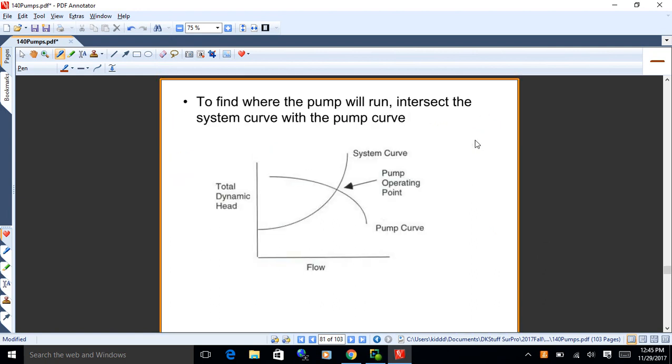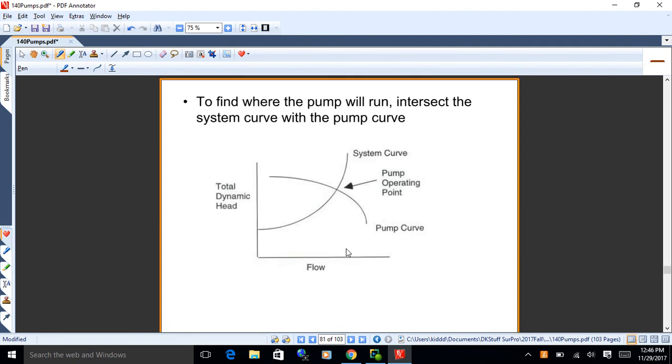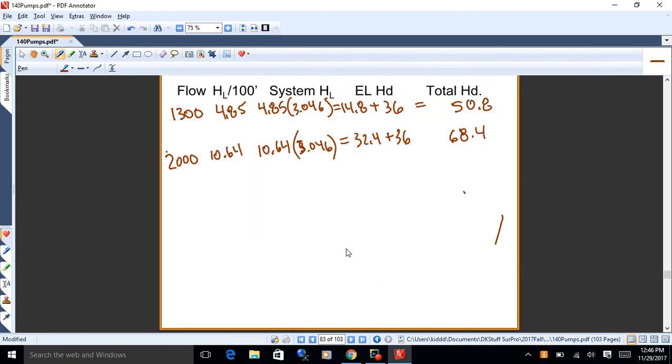Okay. So when the pump gets up to 2,000 gallons per minute, it's at 64, was it? So that's about here. It's getting there, but it's going to keep going. It can still do more, so it's going to pump harder. So let's try 2,400. That pump's just going to keep going harder until it encounters too much resistance. That's the idea. So 2,400 gallons per minute.